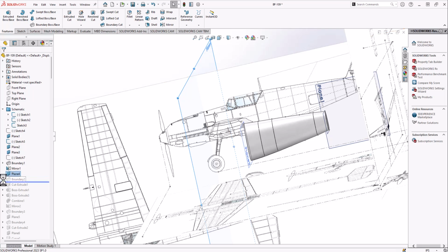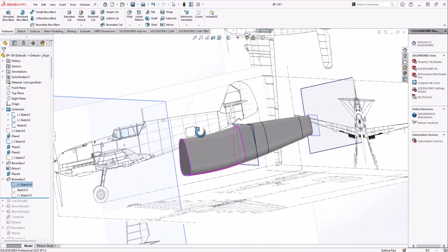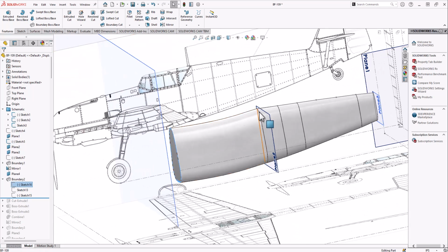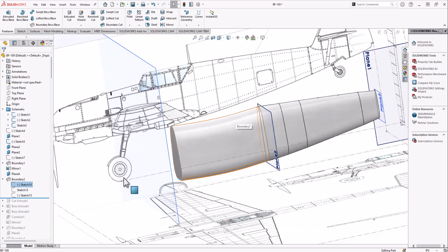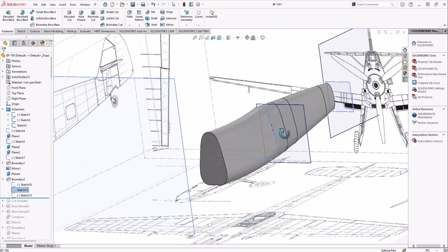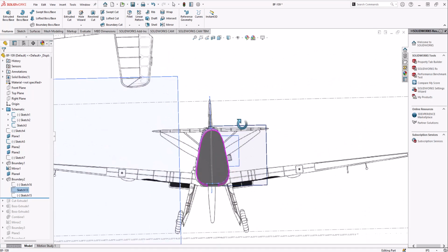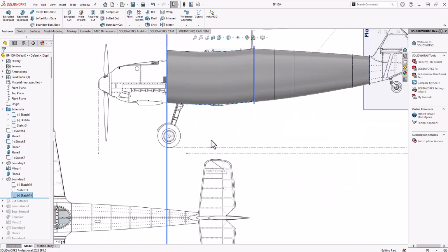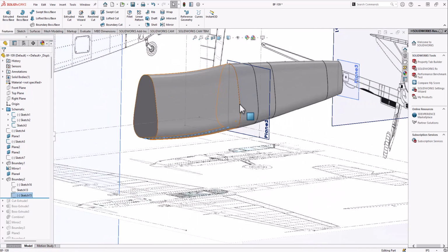And again, I use the boundary function between these 2 points. Here it has this kind of weird shape just because I'm going to cut that out anyway, so I didn't bother to make it really refined. So it's the same process between these two, using a converted sketch of the cross section from this back section, and then just propagating it forward and then creating a guide curve that lined up with the schematic to get this shape.